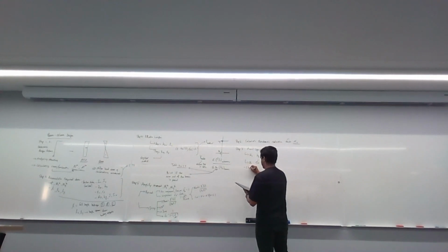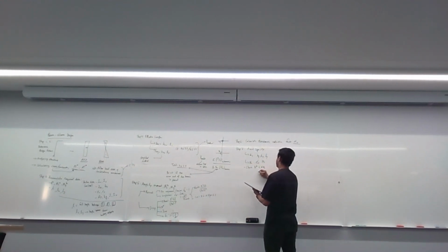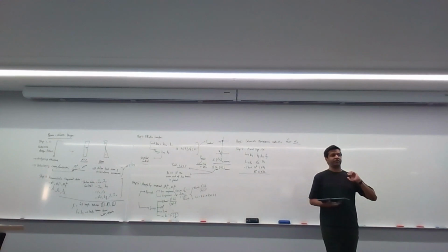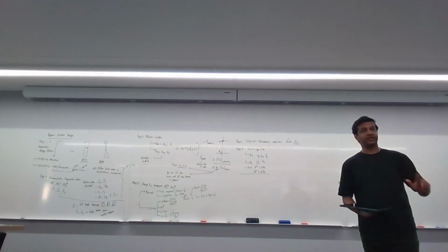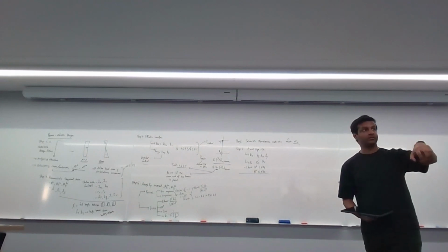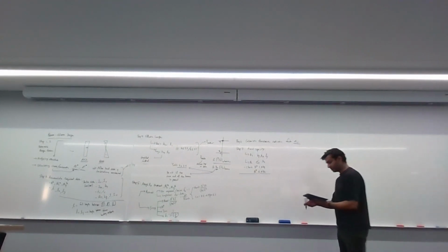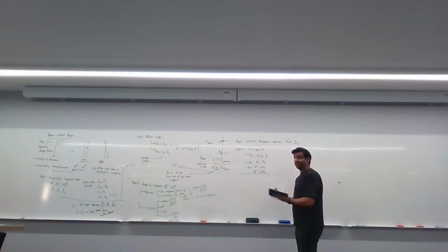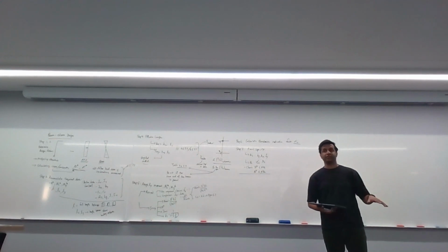At this stage, you check N star lesser than or equal to phi Ns, and N star lesser than or equal to phi Nc. If you get to this stage, then you've done your axial check. So what you've determined is your column under compression loads is safe, both in the section sense and in the member sense. But remember, compression or tension is not the only axial force it's experiencing, right?